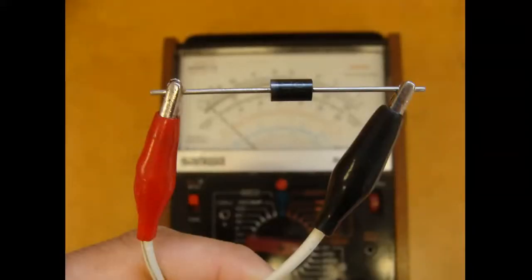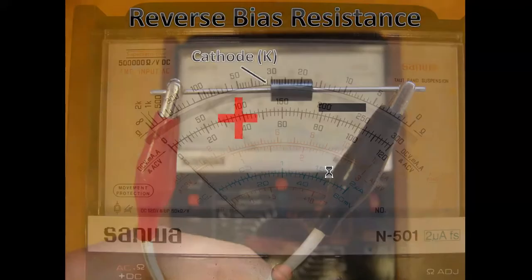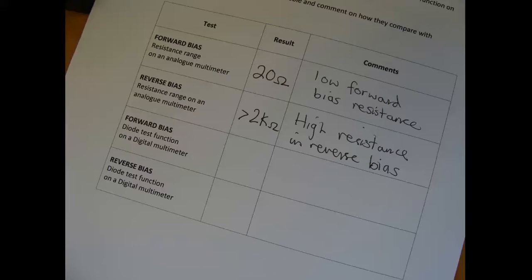In reverse bias, we've got the red lead connected now to the cathode. So the positive is to the cathode, the negative is to the anode, and we shouldn't get a circuit because that reverse bias diode should block any current that tries to flow. If we look at the meter, the pointer doesn't move across the dial, and it's indicating infinity. Now we won't write infinity, we're going to write greater than 2 kiloohms because that's the highest range on that meter.